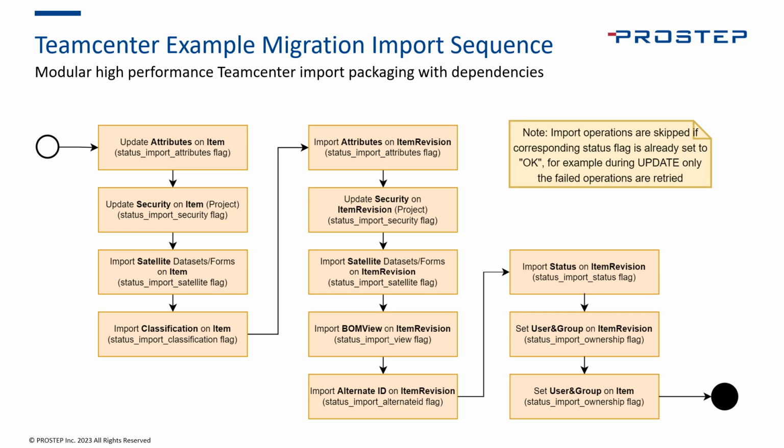Now, it doesn't have to be all done on everything within the database all at once. It could be done that way, but at least package it down so that you can sequence it and make sure dependencies are available, like the item is available with the right attributes for the item revisions and the datasets, and then the CAD that might be associated with that, and flow down that way.